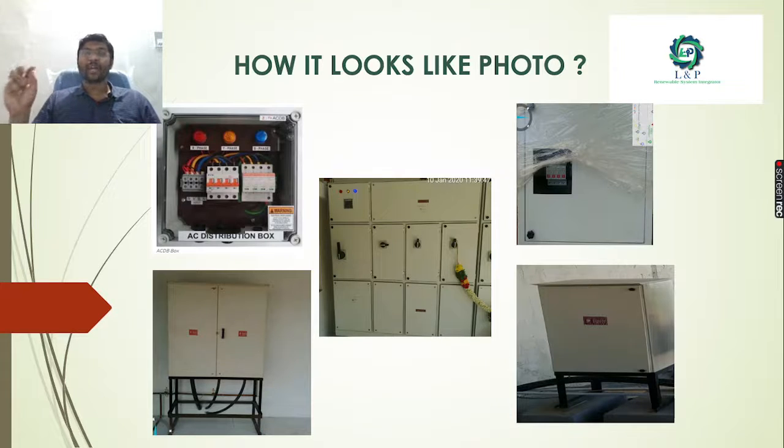If you're going for systems like 400 kilowatt, in such places you can use these 3 in 1 out ACDBs. This helps to identify them separately with the inverters as well as with the strings, and isolation and operating purposes will be easy.